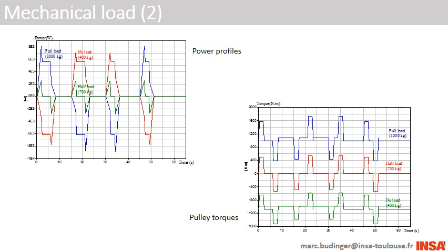Power electronics will have to deal with this reverse power, either by making the system fully reversible or by dissipating power in a resistor. The most constraining case for power remains the one where the elevator is fully loaded. We will use this case in order to size the actuating chain. Maximal speeds and torques are about 55 rotations per minute for this cycle. The motor will have to be associated with a reducer in order to have such high torque, low speed characteristics.